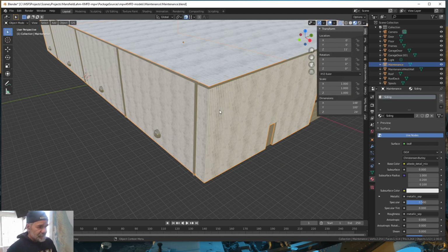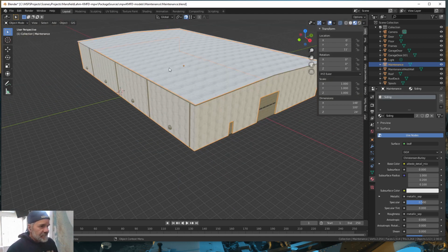It's just that I took a version of the white layer and I brought it into Krita, which is free open source software. That is a Photoshop clone. Link is in the description. But I just took the white layer, copied it into Krita, and colored it a different color and saved it out as a PNG. So now I have a white steel and I have a beige steel. Okay, and then I applied those textures using the UV editing in Blender.